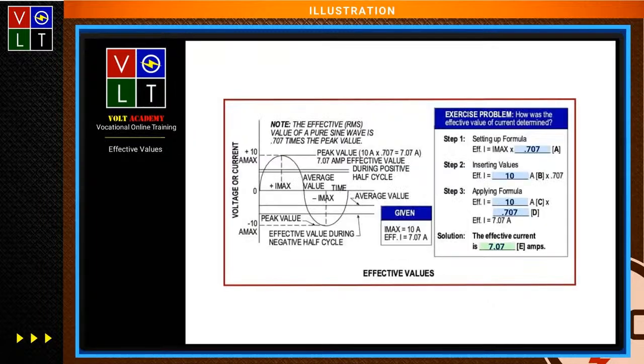Okay. Right. Now, the next thing I'm going to look at here is, we took and put some illustrations here that are going to talk about effective values. Okay. Now, there's a lot to look at here. Now, when you determine the amount of power that's available from an alternating current power source, you have to determine what the effective values are. All right. Right. Now, obviously, when I'm looking at this, effective value does not equal maximum value because that value is reached only once in the cycle.